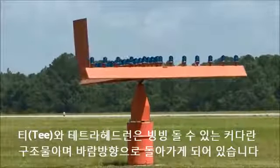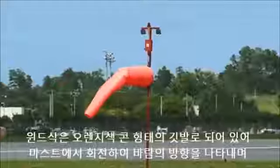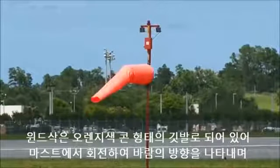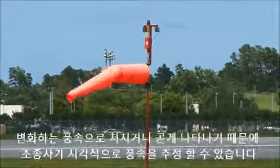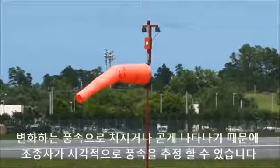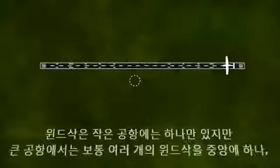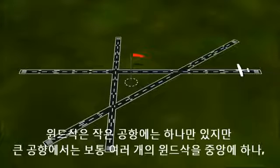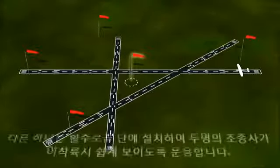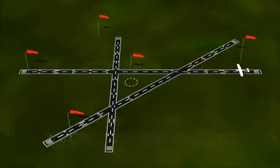free to pivot on their mounts so that they weather vane into the wind. Wind socks are orange conical flags that not only pivot on their mast, indicating wind direction, but will sag or straighten with changing wind velocity, allowing pilots to visually estimate the wind speed. Small airports may have only one windsock, but larger airports usually have multiple windsocks, with one centrally located and the others near the ends of the runways, where they are easily visible to pilots on takeoff or landing.